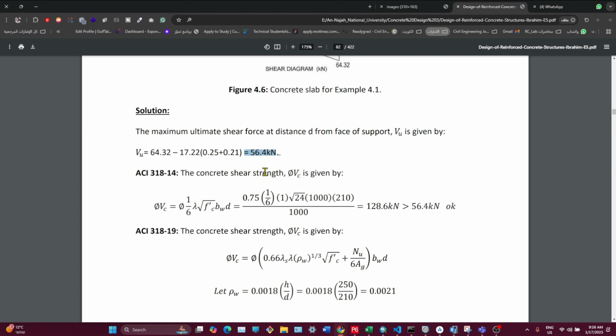We can explain it more if you want. No. Now it makes sense, because we were at the center of the beam, 25 on one side and 25 on the other side. So for us to come to the face of the beam, we have to come back 25. And then when we are there, that d distance, which is in the formula, we have to also add it. It makes sense, very clear, I understand. Thank you. Perfect, I hope.